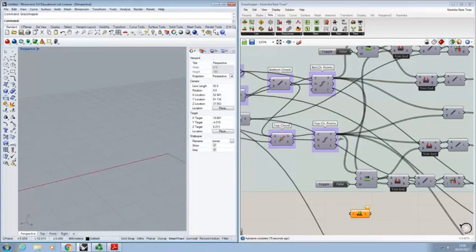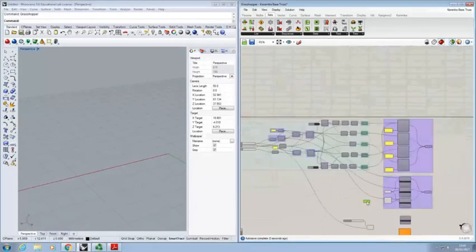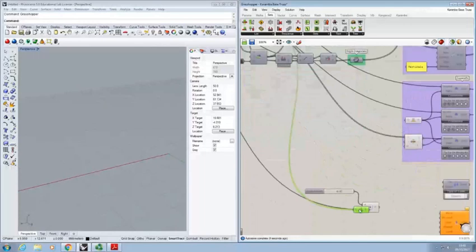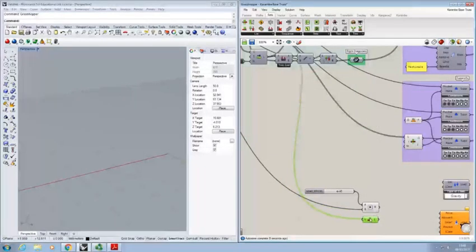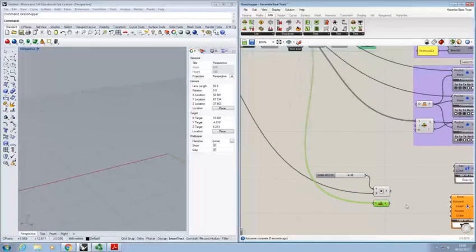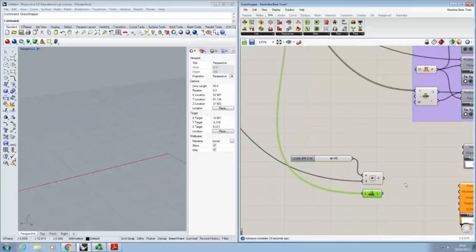And we can plug in that top chord divide curve output, the number of points in the top chord in here, and we get 7. That's in my case. So all we need to do now to get the load per point is to divide the overall load by the number of divisions.